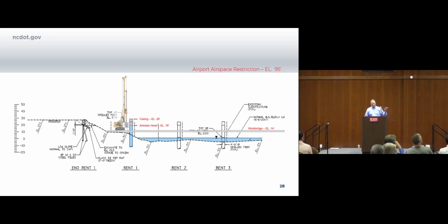And then in talking with Geotech and the contractor, with us pulling our auger up, in and out, losing slurry, we ultimately decided that we needed to have casing at elevation 28 feet, which was 14 feet above the work bridge. Now, a lot of these drill rigs, you want to have your casing no higher than the top of the track so they can go in, get back out pretty efficiently. But some of the rigs are very limited on the headroom to get up and over a casing that's 14 foot up above, drop back down, drill back out.